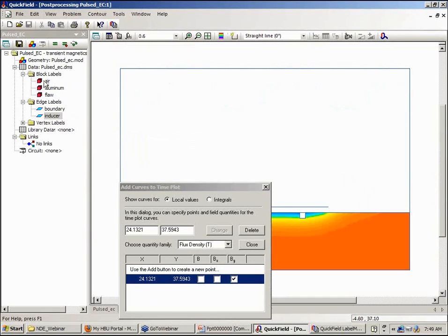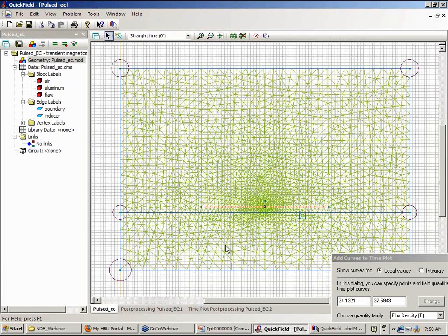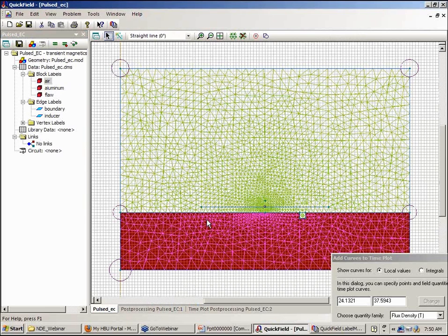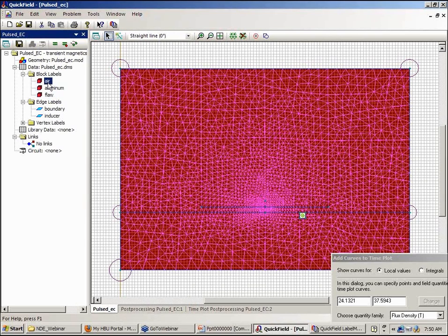One thing I want to do is just look at the signal of the sheet inducer itself. If I go back to my model, my aluminum region, I'm just going to switch it to air. The flaw has permeability of air. Now I'm going to solve this.